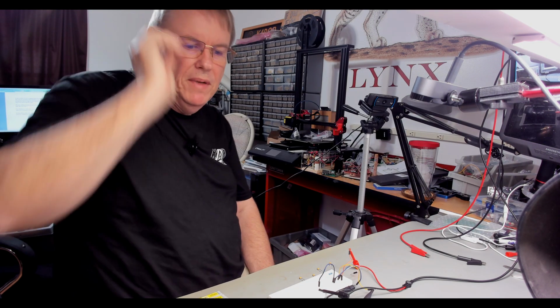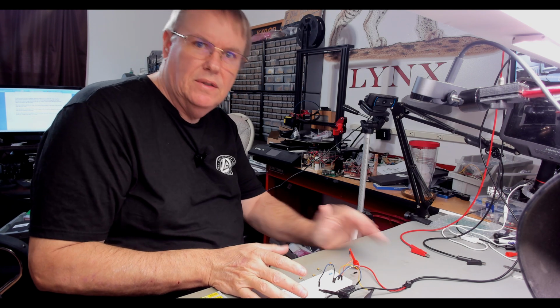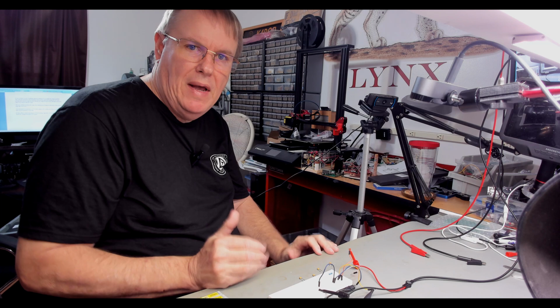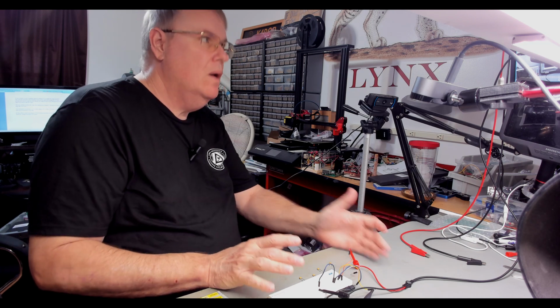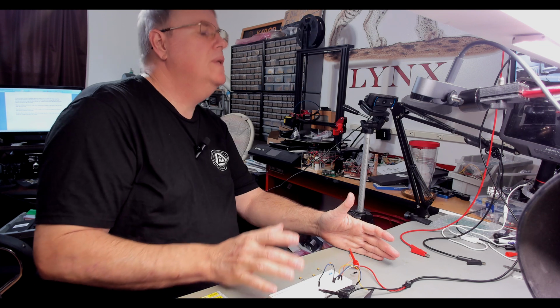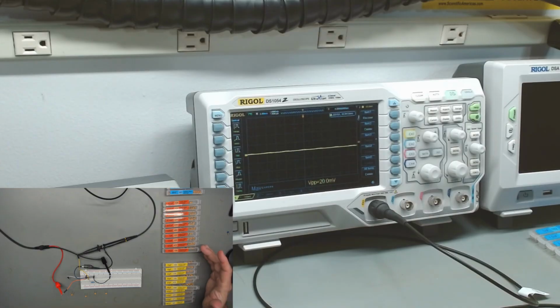Okay, we're back on the bench. I've got the same jig set up that we had earlier looking at the capacitor blocking DC. And now what I want to show you is how different capacitors have an effect on frequency. I've got my signal generator set up to 10 megahertz. I'm putting out 20 dBm. So I've got 4 capacitors. I've got a 10 microfarad, I've got a 68 picofarad, 33 picofarad, and a 10 picofarad.